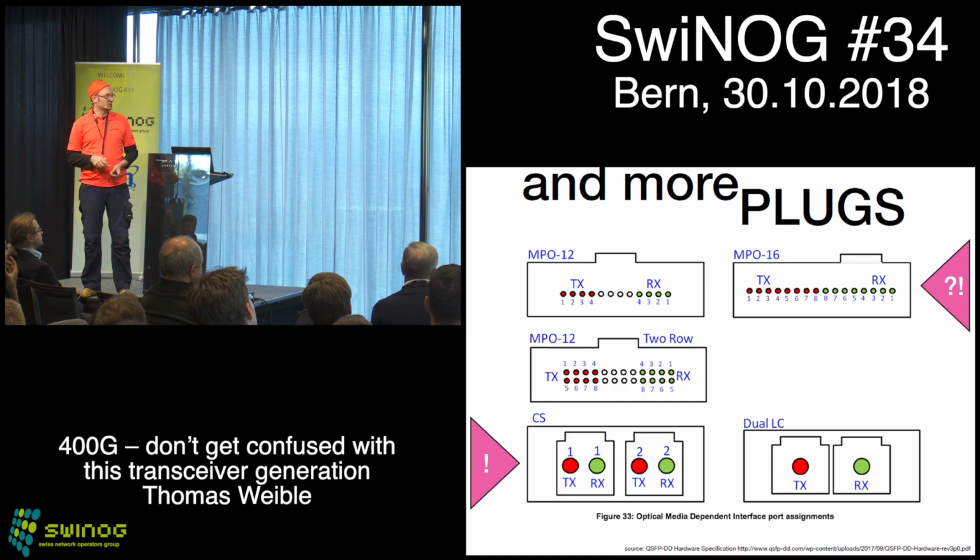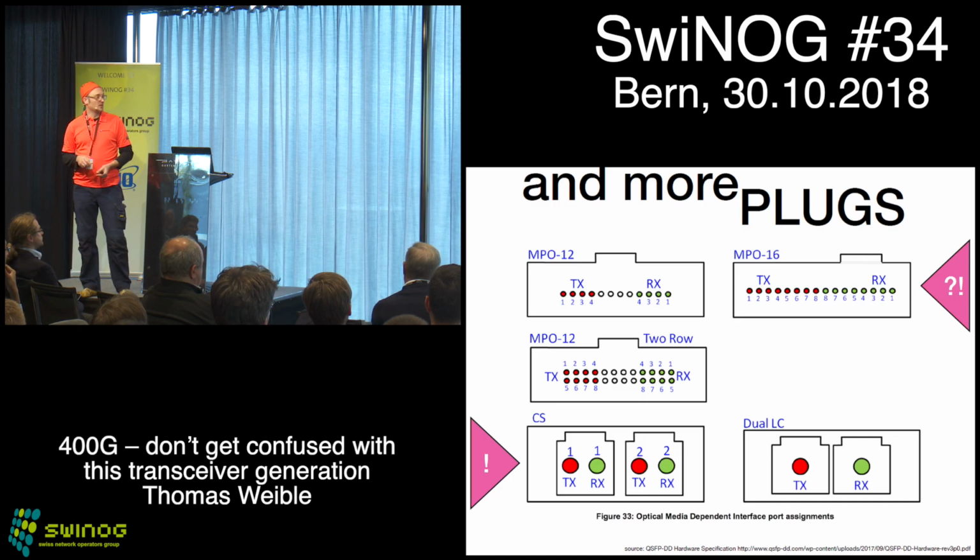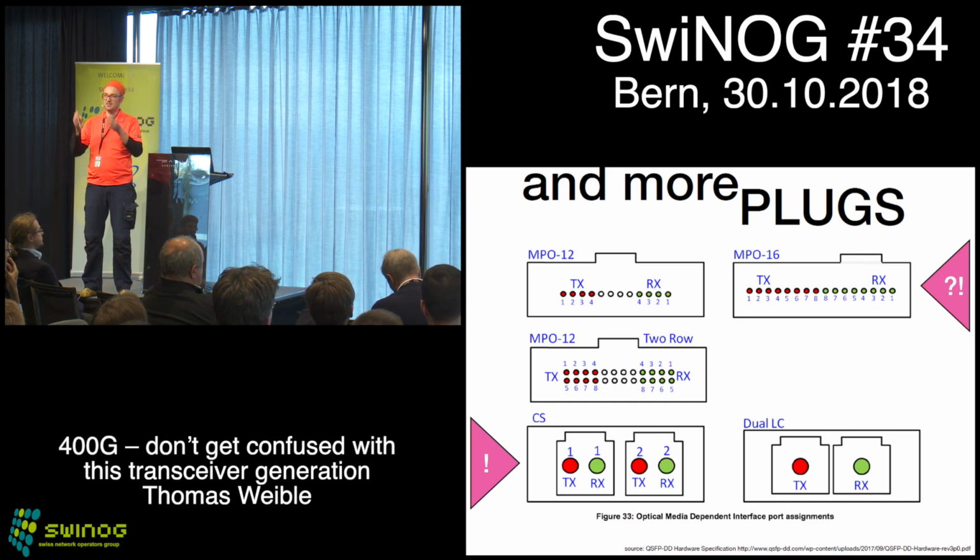For sure, dual LC is still around for single mode, definitely. That's great, these are the good news. And there will be a new one introduced called the CS. I would call it the LC double density, basically, because it's an LC just cut in half of the size.